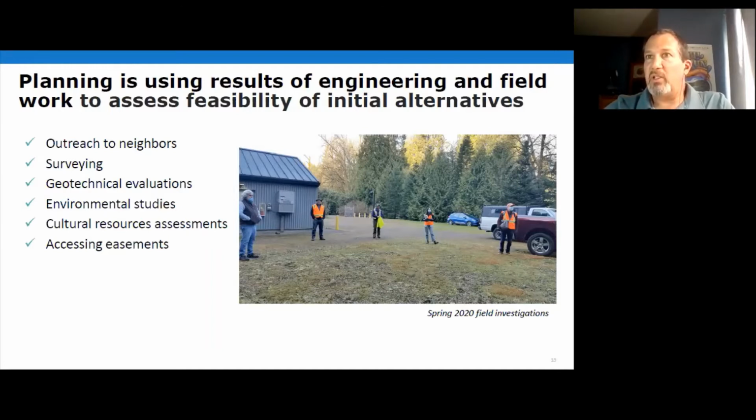We've done geotechnical investigations, and that involves borings that go fairly deep, drilling holes out there. You've seen some drill rigs on a number of different properties and in the right-of-way, and they're looking at the soil conditions along those alignments to look for where groundwater is, if there's been landslides, and what types of soils are there, because the different soils have different strengths and will react differently in earthquakes and seismic events, as well as if there's been landslides there and how they react.